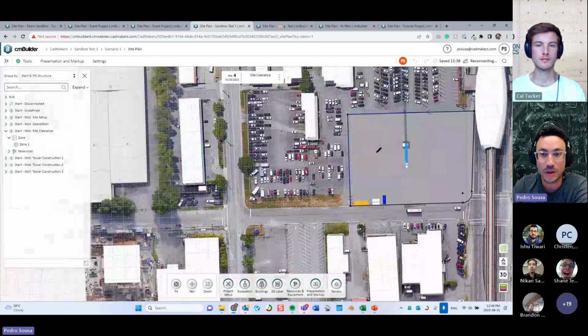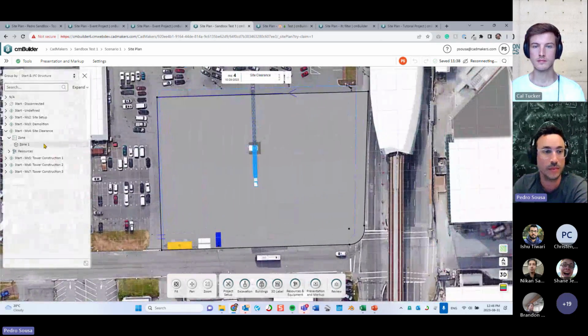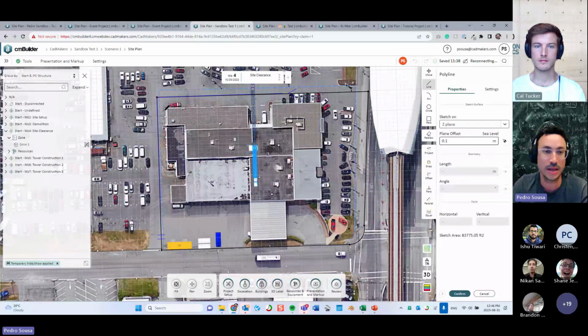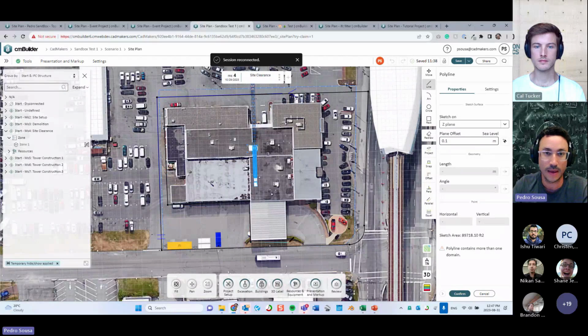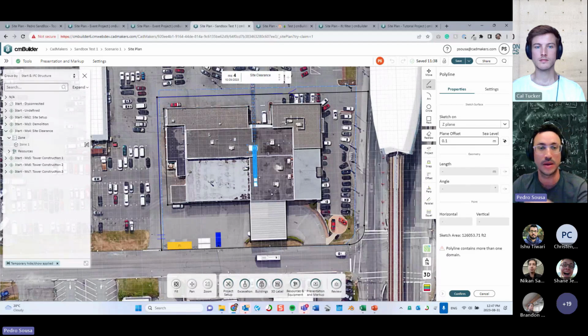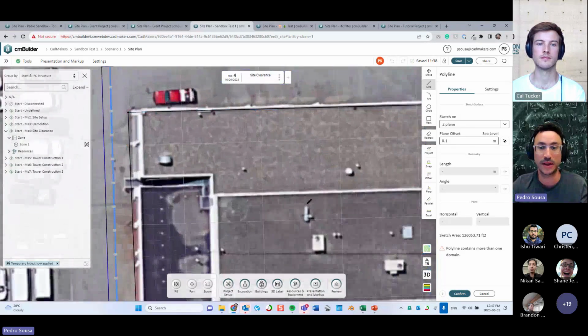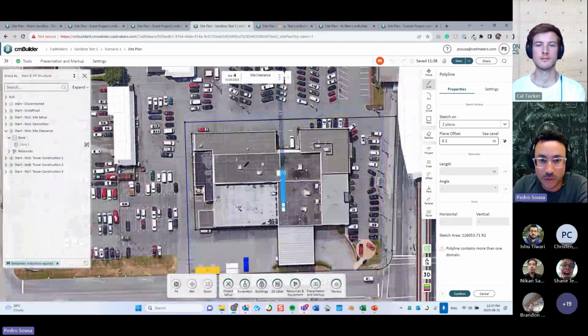So what you can do is simply create a zone that will have the shape of the building. So let me position my camera here for a second. You can create a zone that has the shape of that building, and within that shape, you define a color of that zone with a transparency that is similar to the color of your background, right? So it's not always going to be perfect.